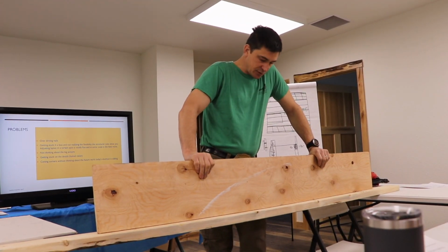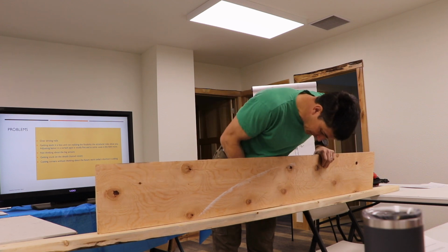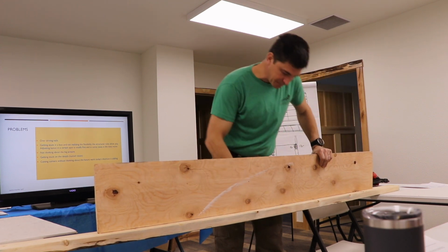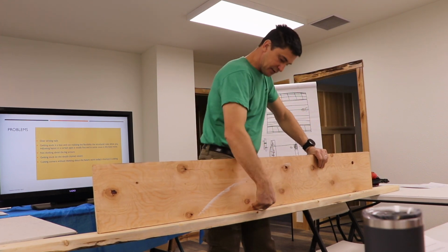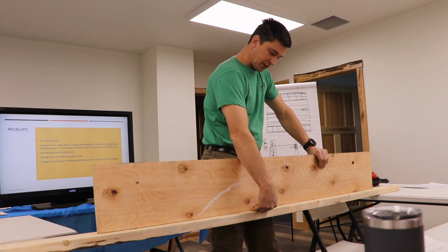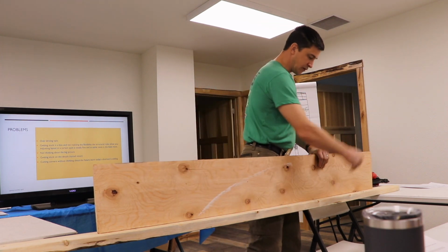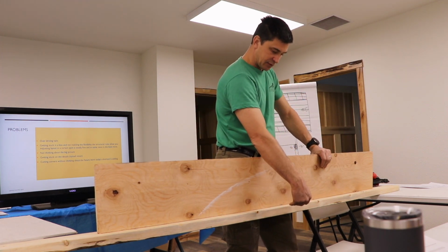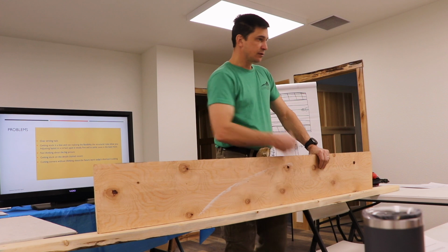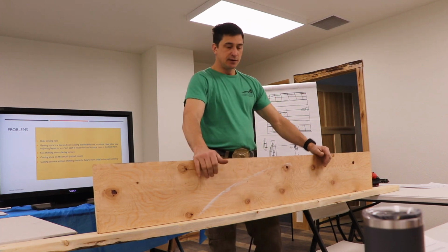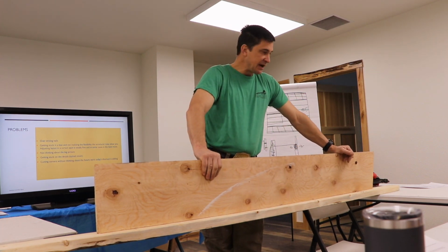There's always a gap between it. Then they'll butt a 2x4 tight into that gable end truss and nail it down, and now you've got this gap that goes between your backer wood and your gable truss right to the outside, and the wind just blasts through those things.